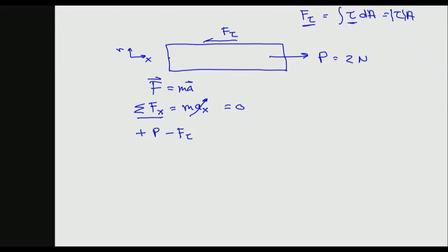So this negative sign here accounts for the direction of tau, which we know just physically, it's a shear force acting on the shaft, right, opposing its motion. And then that's equal to 0. So then you just simply get, P is equal to tau A, as you want to, right? The problem is some people immediately start from here. Okay, and so you're missing out on some very basic stuff, which you guys, for such a simple problem, can do in your head.